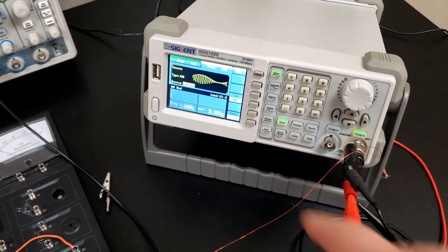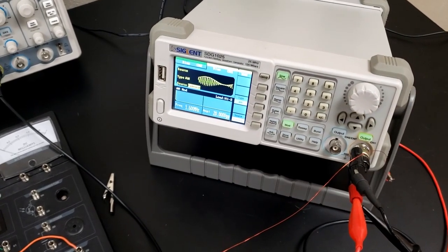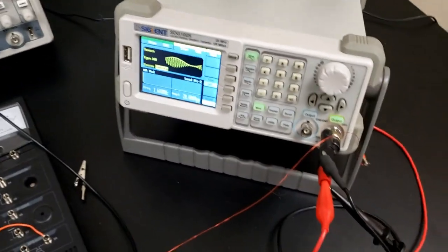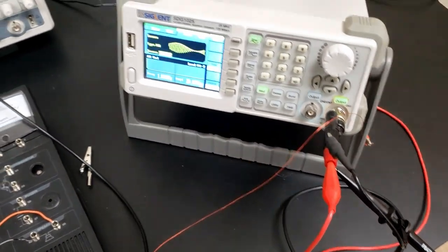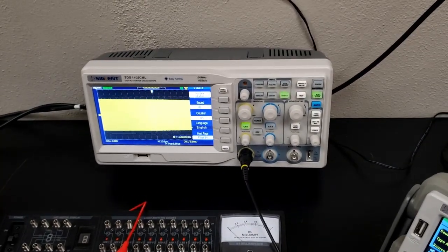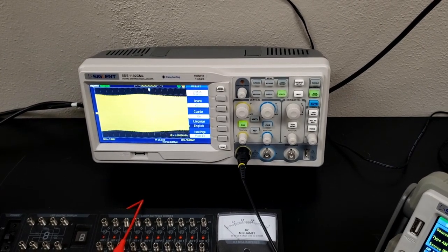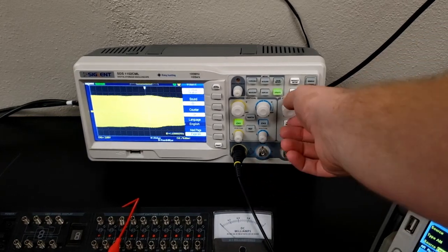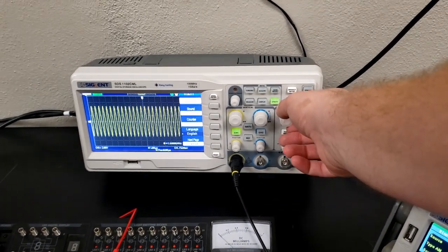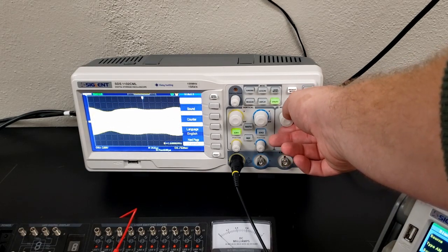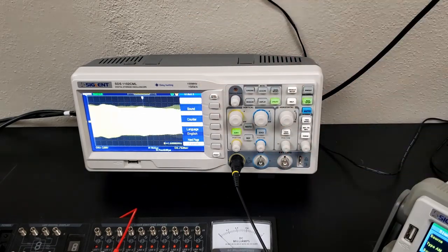Right. So right now we have this modulating our signal. We have our phone plugged in, playing a song that you'll hear in a second, hopefully. And I also have the oscilloscope hooked up to this thing. So if we look at the oscilloscope now, you'll be able to see that carrier wave being modulated. So you can't actually see the individual waves of the carrier wave because the frequency is so high. Let's see, if we change our horizontal axis, you might be actually able to see it. There you go. But it's easier to see that envelope or that modulation if we make it so small that you're only able to see that envelope of it.